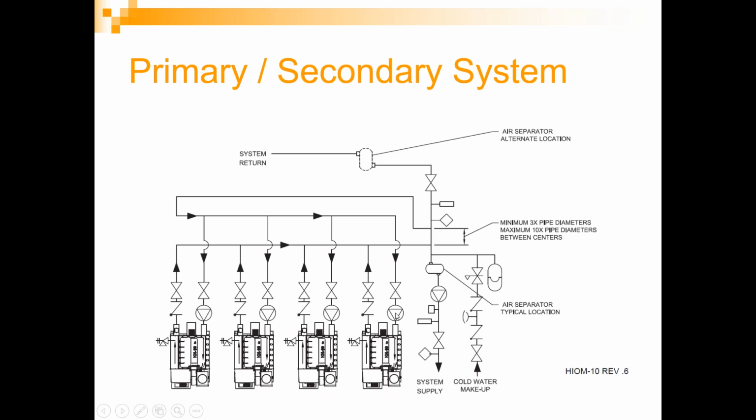And now we also have the individual circulator on each one of the boilers. Now this circulator would typically be controlled from the boiler with a pump delay relay, controlling this pump on and off and leaving that pump run for 10 to 15 minutes after the boiler stopped firing to carry away any residual heat.